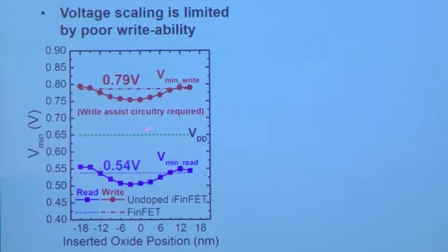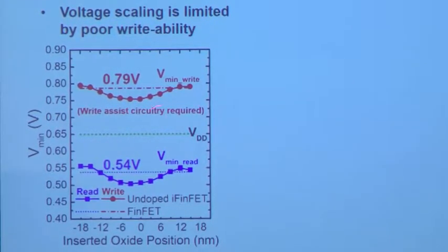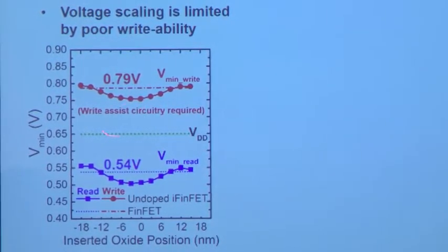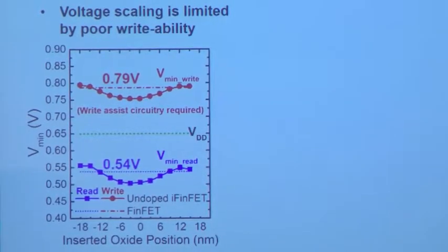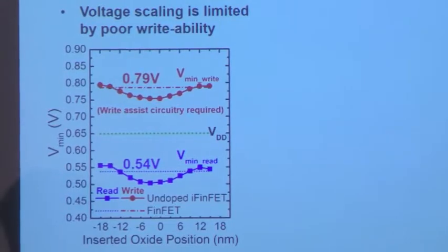You can if you implement write assist circuitry. So if you boost the word line voltage during write, or you purposely lower the voltage of the inverters during the write process, using these circuit techniques, you could operate a minimally sized 6T SRAM cell at lower voltage. But this write assist circuitry requires overhead, in area and operation of the SRAM cell.